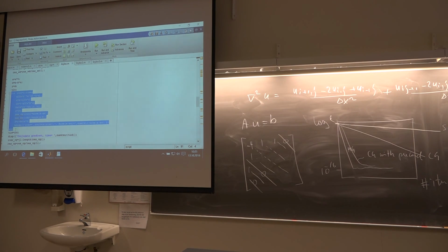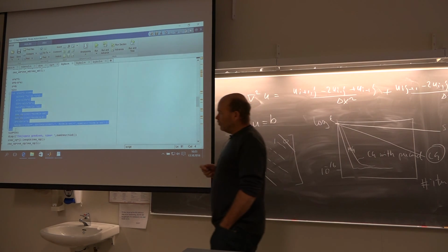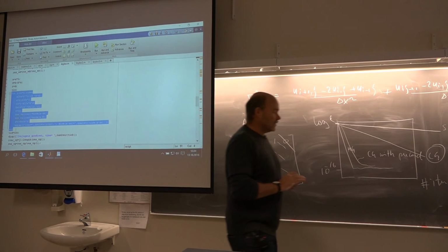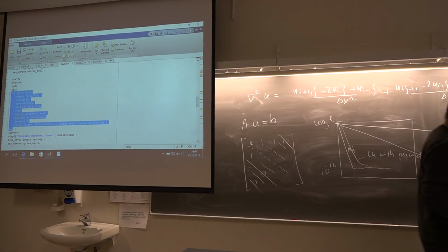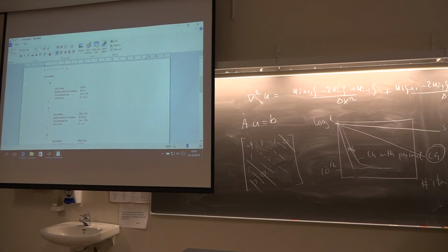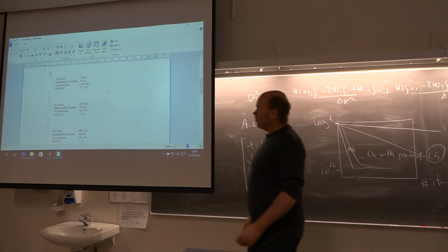That is a very strong thing with these conjugate gradients and steepest descent. Actually the conjugate gradient is very, very small. Of course, it will be more advanced when you use a preconditioner, but very, very efficient. And these methods, the conjugate gradient methods, are typically what you will find in OpenFOAM.